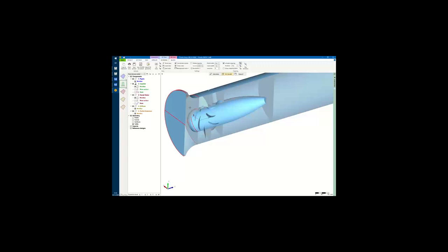We apply some script logic to modify the STEP files or to convert them into SpaceClaim file documents and apply the named selections. And then the input into the Ansys meshing system is a SpaceClaim file format.